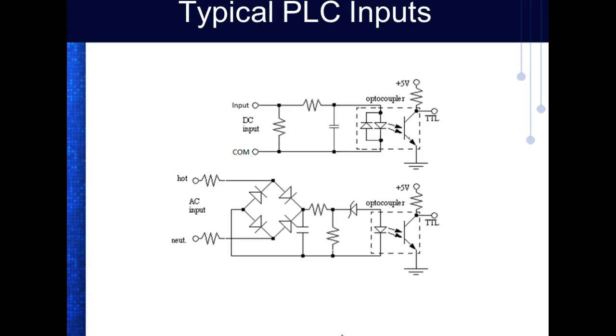Now hopefully you have another port that you're not using. Normally on a PLC, we usually don't use all the ports that we have available. If I screw up one of my input ports, what can I do? Move to another one, and you'll have to redo your program, right? You understand? But that's better. You could be back up and running before you come out there and have to do that. So these are called optical couplers or optical isolators.